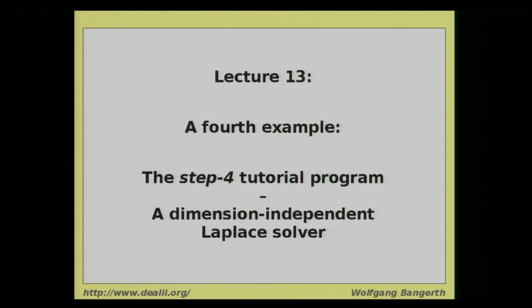And of course, there's an enormous benefit to this because finite element programs are very large. I mean, they have tens of thousands, hundreds of thousands of lines of code, and if we can write it only once and test it only once, we're certainly twice as well off as if we had to write everything twice for the 2D and for the 3D case, and maybe for the 1D case as well, although that is not quite as important. So what I would like to do is show you how you build a code that runs in 2D and in 3D and solves the Laplace equation. And that, of course, is step 4.